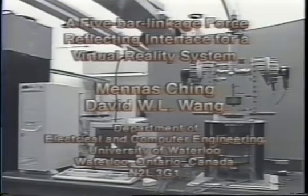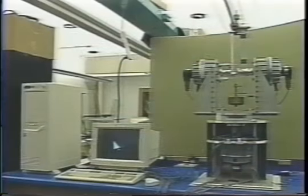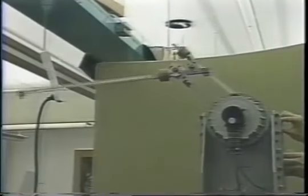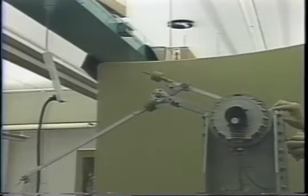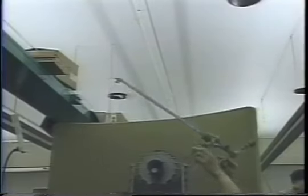At the University of Waterloo, a 5-bar linkage haptic interface has been designed as part of an inexpensive virtual reality workstation. This input device allows a user to touch virtual objects in the real world. This robot has been designed to be dynamically decoupled and gravity balanced in all configurations. This allows all gearing mechanisms to be eliminated. Inertial effects are minimized by making the robot links very lightweight.